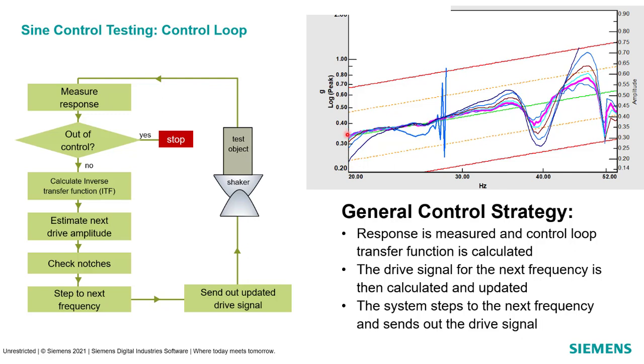Typically, you're going to start at low frequency and sweep up through to high frequency. It's going to use that transfer function initially, but the control algorithm will continuously, throughout the entire frequency range, update that transfer function. So the G's per volt, as we talked about earlier in the presentation when talking about the self-check and the transfer function, it's a G's per volt transfer function: DAC out voltage versus the G responses.